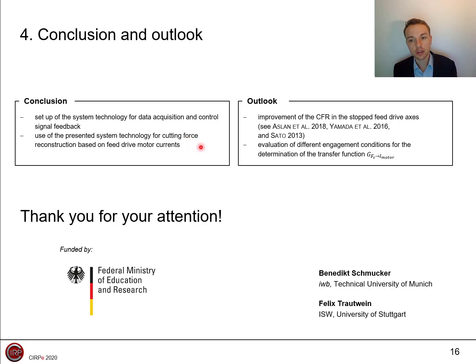For the reconstruction of cutting forces, the transfer behavior from the tool to the feed drive motors must be known. This transfer function was determined using slotting tests and air cuts. For the moving axis, the cutting force reconstruction already worked well, but for the stopped axis, further research is necessary. Aslan, Yamada, and Sato already showed interesting approaches here.